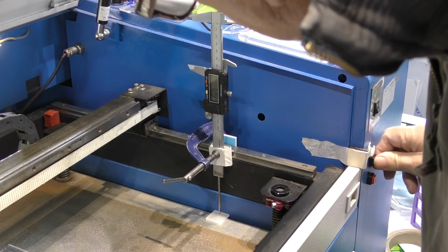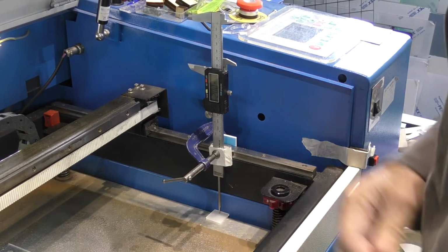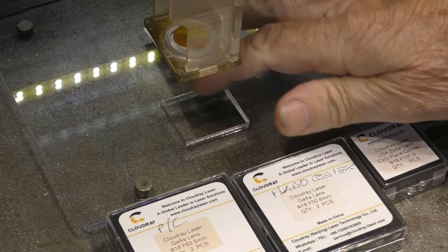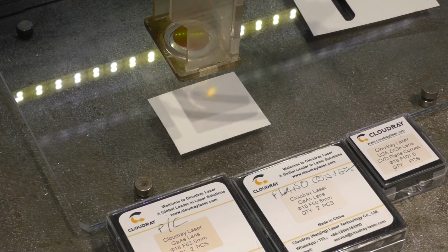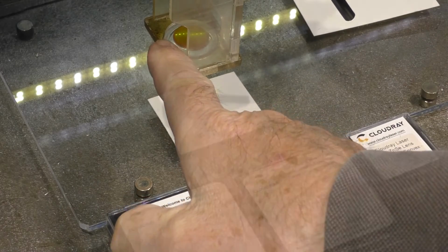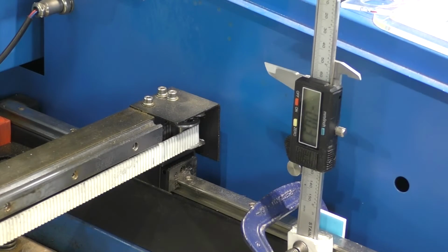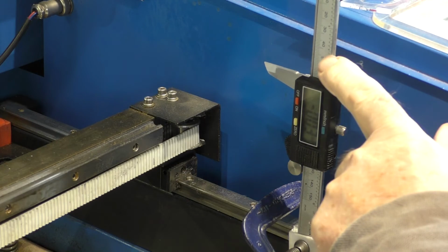And if I set this to 0, like that, 002, and I put my thin piece of card, and I've put it over a hole here, so that when I burn through with my tests, I don't have anything underneath. And then I'm setting the focal distance of this lens with my little dot test to try and get the correct dynamic focal distance. I set my dial indicator here to 0. Okay, now I can drop the table down by 20 millimeters below the focal point,